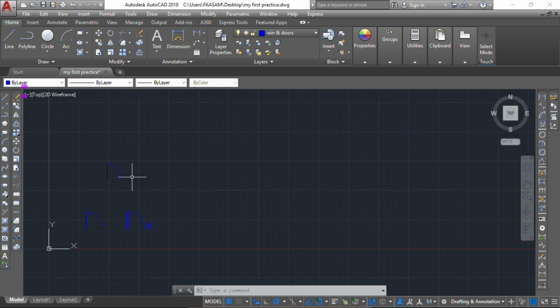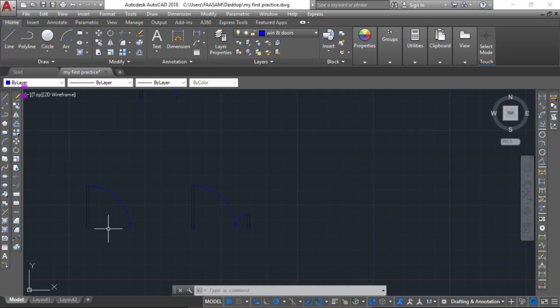And meanwhile, anything on the plan, any diagram you're making on the plan does not require the height. The height is only required when you want to do your elevation. So as we are looking at the plan of this door here, it's only 900. The height is not being indicated because it's the plan, but once we create the elevation, then we'll be including the height. We'll be using both the height and the width.